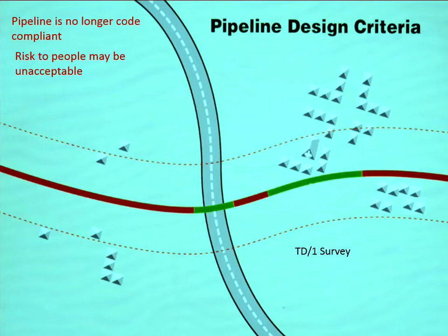So we're talking about a minimum distance, that is the distance which has to exist between the pipeline and any occupied building. And then the different curves are for different diameters of pipeline. So you can see that as the pipeline diameter goes up for the same pressure, the distance starts to increase.